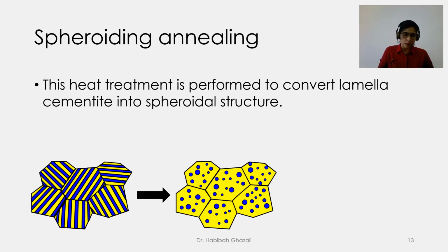During the solidification of steel, we know that at room temperature, we will have some portion of the microstructure, or if not for eutectoid steel, we will have all of it in the lamella microstructure. So we will have ferrite and also cementite in the layered cake microstructure.